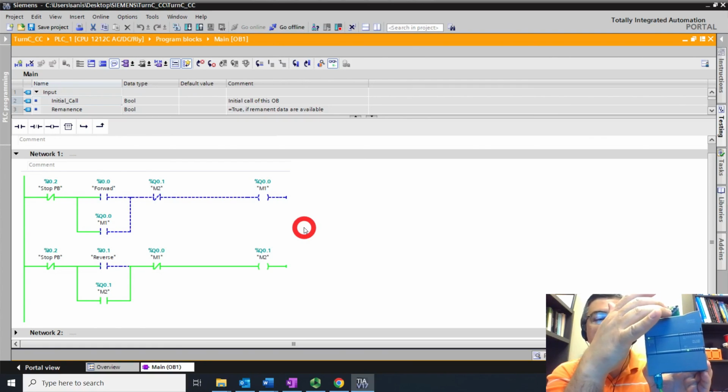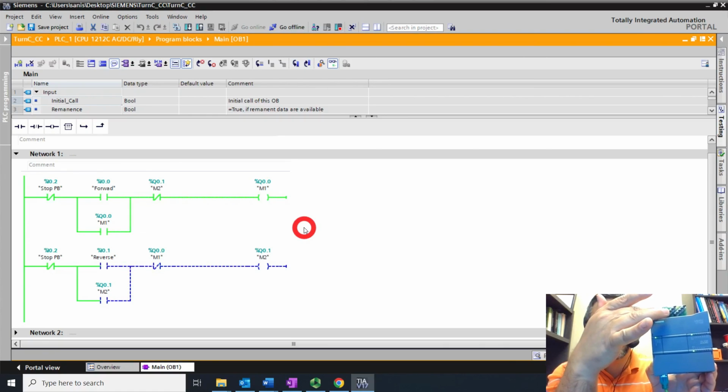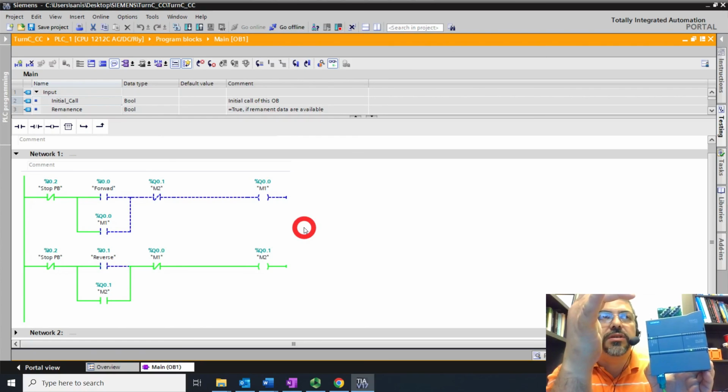If I want to go forward, I first should stop it, then I could move forward. I'm doing that fast. Right now it is in the forward. I push the stop to stop it. Then I push the reverse and I'm able to turn that in the reverse direction.